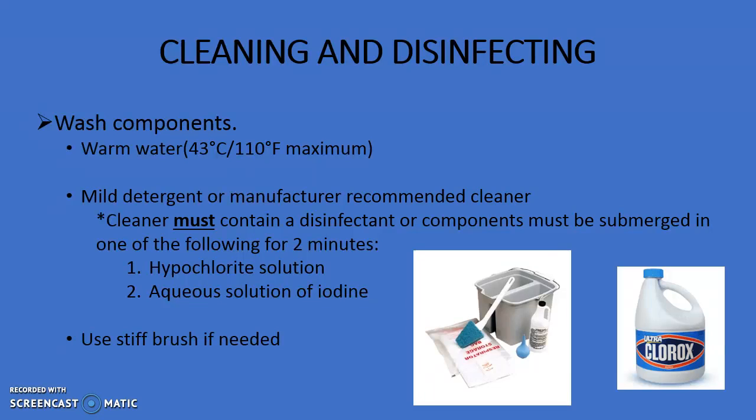When the cleaner used does not contain a disinfecting agent, respirator components should be immersed for 2 minutes in one of the following. Hypochlorite solution, made by adding approximately 1 milliliter of laundry bleach to 1 liter of water at 43 degrees Celsius or 110 degrees Fahrenheit, or an aqua solution of iodine made by adding approximately 0.8 milliliters of tincture of iodine to 1 liter of water at a maximum temperature of 43 degrees Celsius or 110 degrees Fahrenheit.